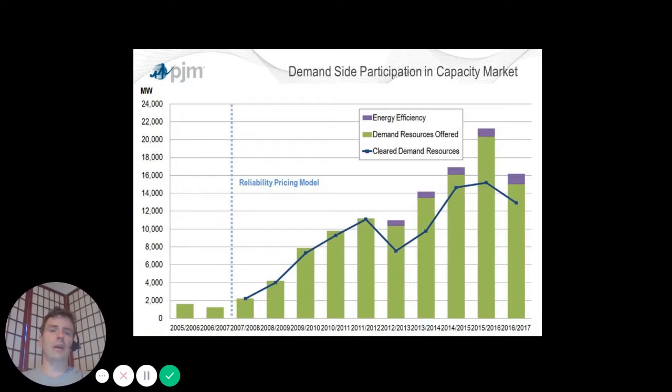But if thousands and thousands of people volunteered to have their electricity shut off just momentarily during the hottest part of the summer, that might make a lot of difference. In other words, it would give the system the ability to push a button and reduce electricity demand, which is a lot like pushing a button and producing electricity. And so this type of resource is actually becoming an accepted way to meet peak system demand in different power systems.